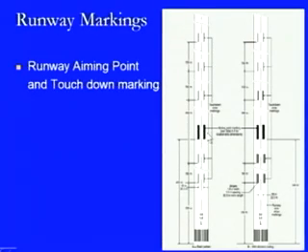This bigger strip is provided at this location, usually at a distance of 400 meters from the end of the runway strip, and from this direction there is going to be a landing. So, this is a runway number marking which is 20 L, where L means left, and 20 defines the angle at which this runway strip is provided with respect to the overall angle of space, that is 360 degrees. So, it is 200 degrees in this case.